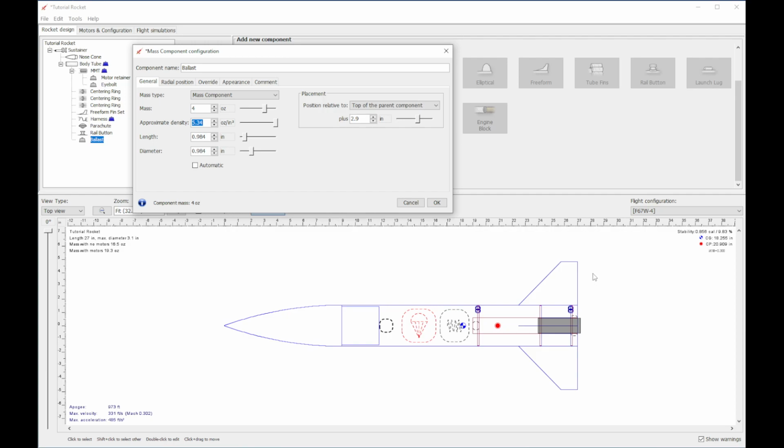I think this rocket would probably fly and be aerodynamically stable, even though my stability margin on the pad isn't at 1. And that is because this would be considered a short, stubby rocket. I don't know the technical term, but stubby rockets are rockets where your overall length to diameter ratio is, I can't remember the benchmark, maybe less than 6:1 or something. And in those cases, rocket stability is also affected by the base drag of the diameter of the body tube. And so you get some wiggle room there.